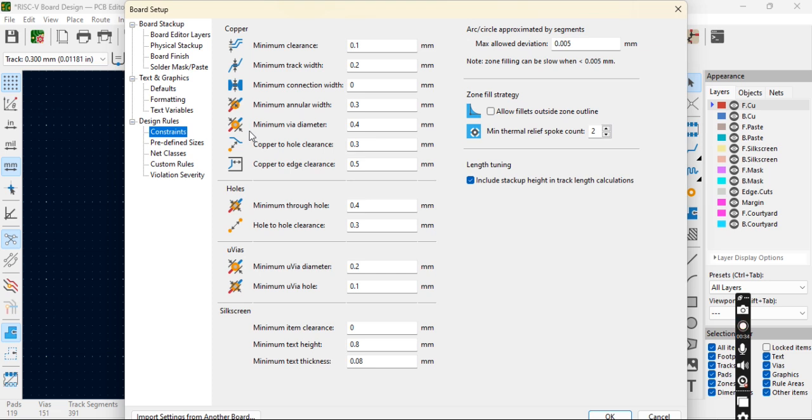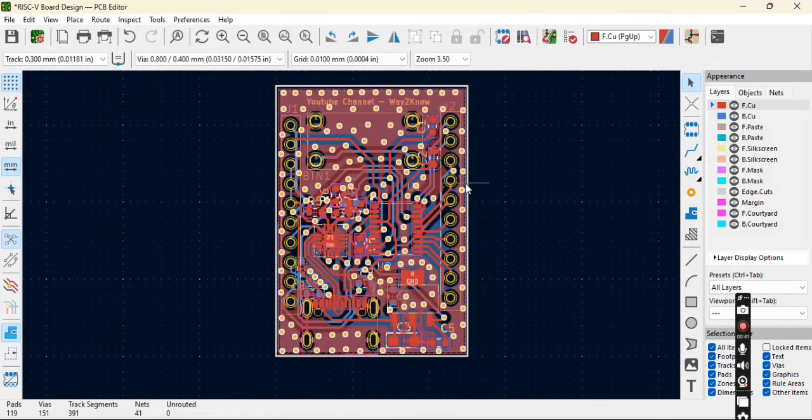Design rules, as we talked about in the previous videos, are basically the rules that need to be followed so that you can have a PCB which can be manufactured. Now, once the PCB is done, we have to see whether these specific design rules that we set are followed or not. This is a very important step before you release the PCB.